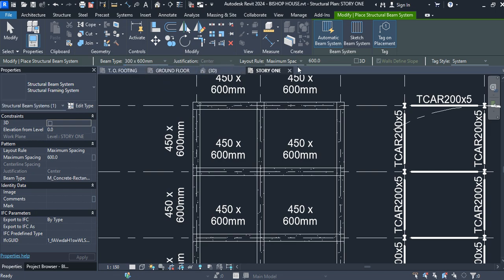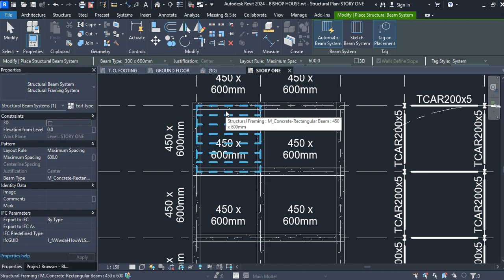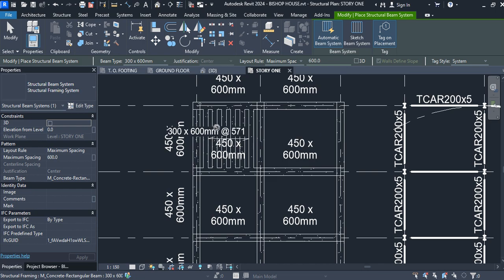And just the specification must be center line space, maximum spacing, then at 300, then the system, main system. So when you hover here, it gives the span direction. So either side of where you hover at gives the span direction. So we shall select here, and this has given us span direction with our tag.